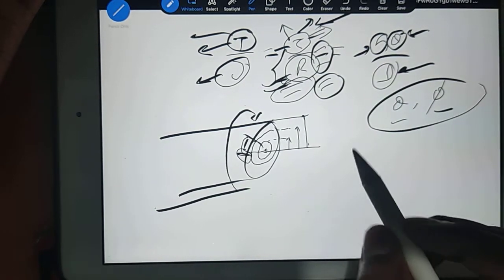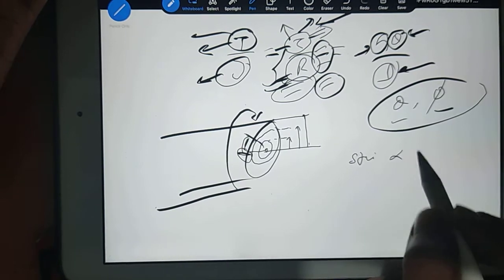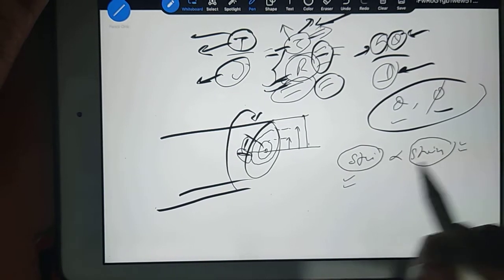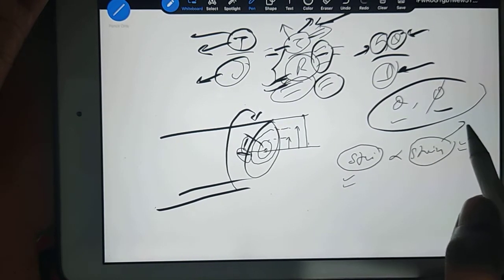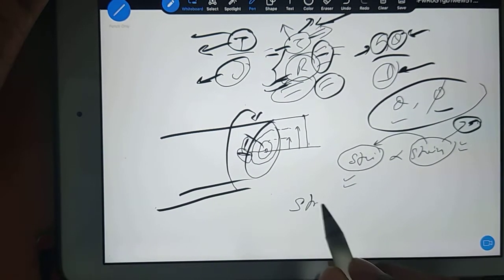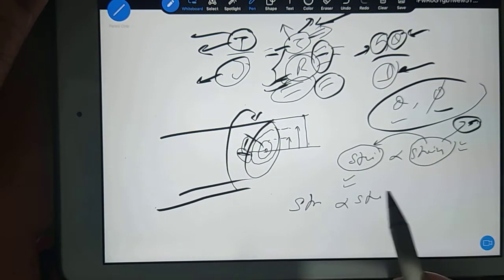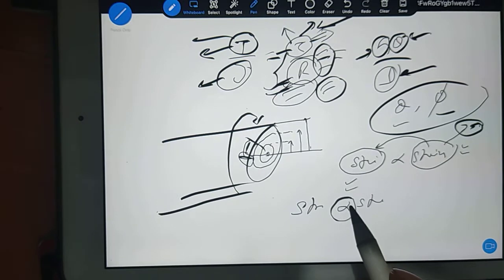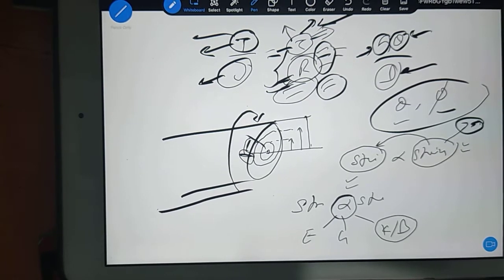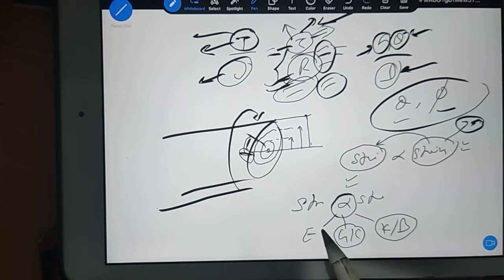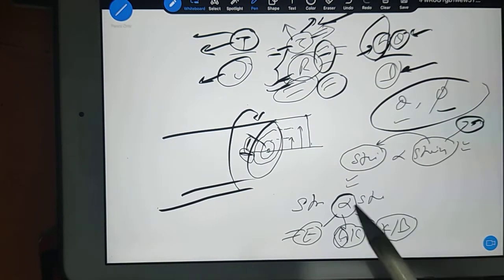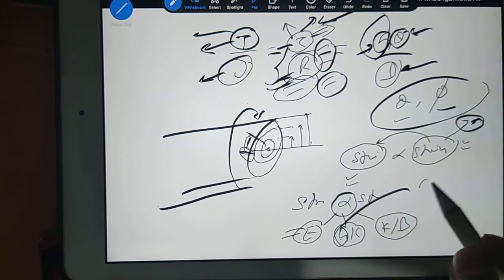What is G here? You know stress is proportional to strain. It depends on what kind of stress we are dealing with, according to that we will have that kind of strain. In real life we calculate strain by using strain gauges, and by applying Hooke's law we can calculate stresses. So stress is proportional to strain, this part is clear, but when you remove the proportionality sign, you get elastic constants. That elastic constant is E, G, or bulk modulus K or B, whatever symbol we use. In some textbooks G is replaced by C. For Young's modulus they always use capital E. This G value is known as shear modulus or modulus of rigidity.